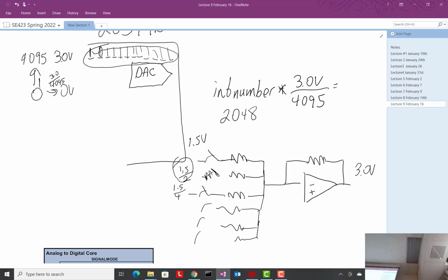So anyway, that's one way. But we can drive motors with DACs. There's amplifiers that take voltage in instead of PWM in. So a lot of different things out there that we can use for DACs. So drive a different voltage. A lot more data, isn't there, in a DAC signal than just a high and a low? There's 4,096 different signals in there. So we got more that we communicate with. Good. Okay, so great. That's the DAC.